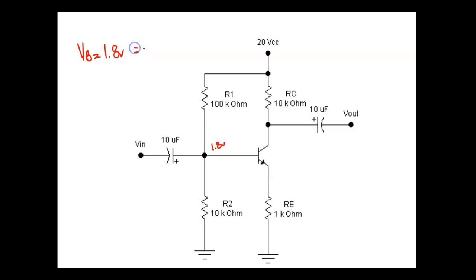So I would come over here and say 10K divided by 100K. The Ks cancel, right? Then these two zeros cancel. So it's going to drop about 1/11 of the voltage. 1/10 would be 2 volts. You see that? Then I multiply this times 20.